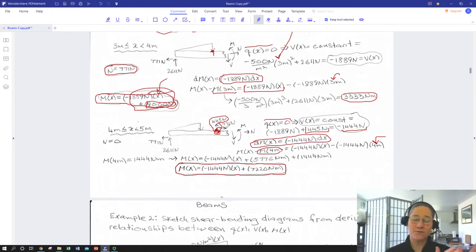So if you look at internal to the beam as we cross that point at 4 meters, that point applied force that's heading up at 30 degrees has now completely provided all of the countering force to the horizontal force to the support at A, and that normal stress in the beam should drop to 0. So basically that would be something important to note, that if we're looking at axial stresses in the beam, N dropped to 0, so our sigma XX dropped to 0 as we went through the point at x equals 4 meters. So from 4 meters onward, N equals 0.